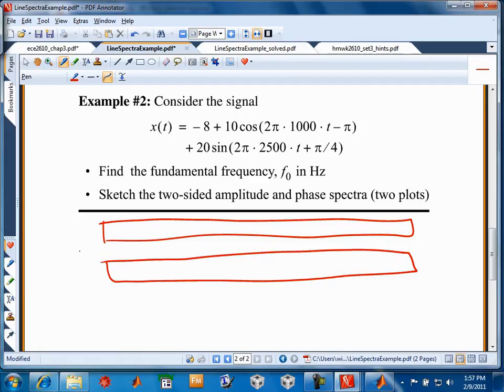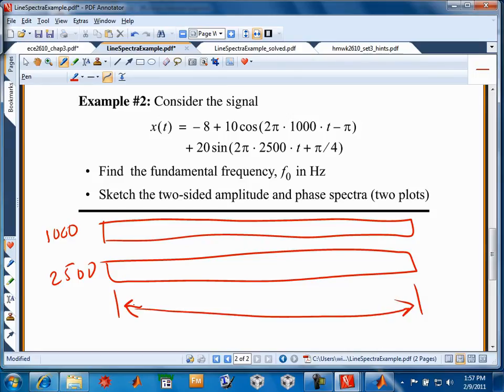In this case, because we have a 1,000 hertz and a 2,500 hertz signal, if we were looking at this plot like you do in the lab exercise, you're looking for this period T naught, where you see the waveform repeats. You have a squiggly line, and you can notice just from eyeballing it that it repeats every so many seconds. Call that T naught. That's the smallest period, or the smallest value where the waveform repeats.